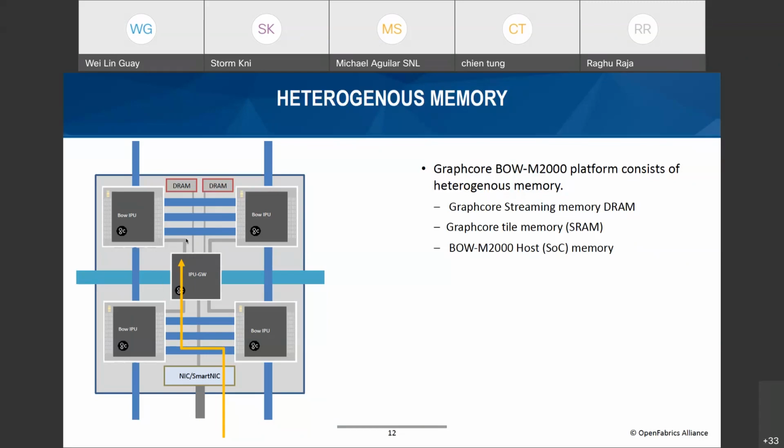So how can the software frameworks feed data to the different memory regions pinned to different memory subsystems? With the BSP model, as discussed by Doug, the Graphcore Poplar graph compiler uses compiled communications, which means all the host IO traffic patterns are known. The selection of the memory to use, either landing directly into the streaming memory or the tiles memory, is transparent to the application users.